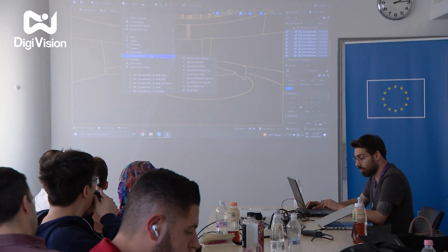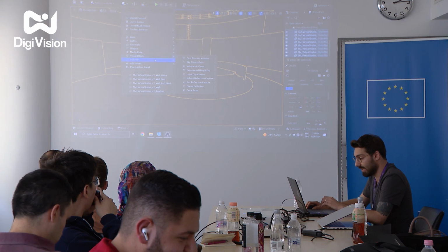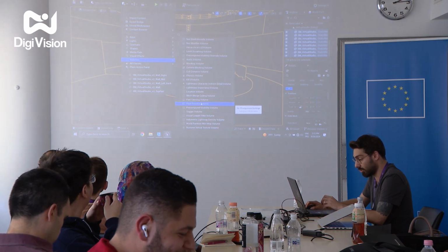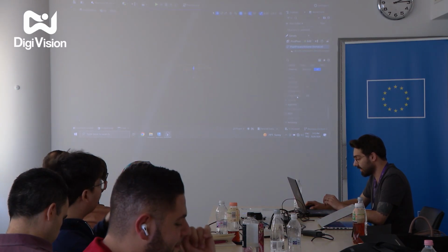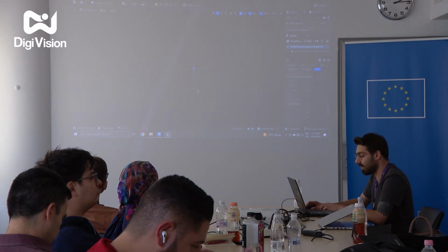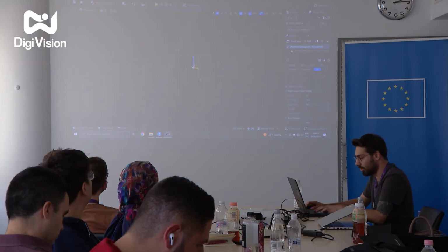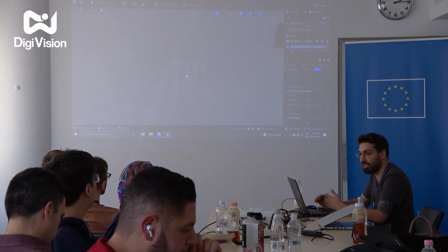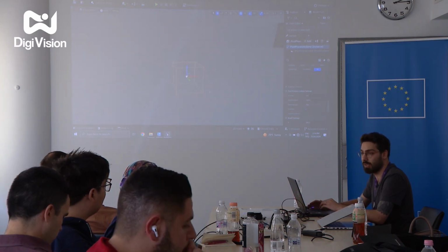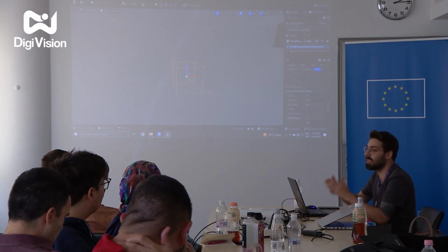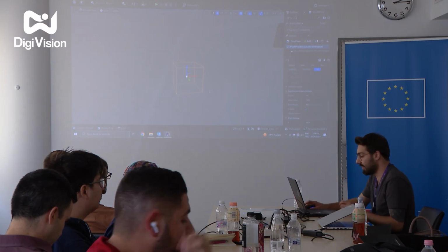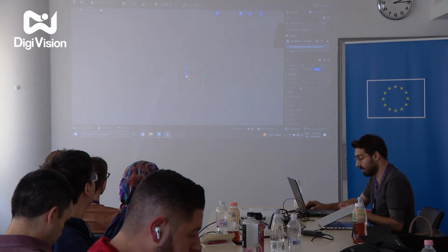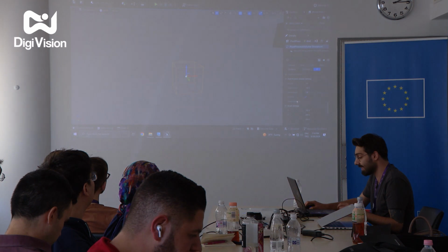I am just going to add a volume called post-process volume, and I am going to set it to 0. If you remember the last session of our training, it's a volume-based actor, so when we make changes on this volume, we are only able to see them when we enter the volume. To avoid that and make it global, we just need to enable the infinite extent button.